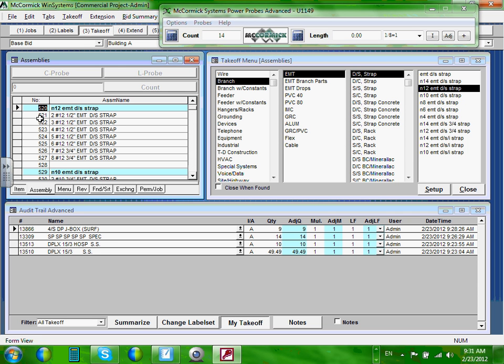Okay, we're going to do that over what I've done. Okay, so I'm going to go branch circuit. I single-handedly, Mr. Curdy, decided to use EMT, which is 99% of what you guys are going to be using. EMT. DS is the strap that comes with it, steel strap. We're going to click the strap, the first one. And here's my option. Number 14 conductors. All the conductors are here, number 14. Don't do that. It's usually number 12. That's your default. Because almost always your branch circuits are number 12. Your branch circuits are always number 12. Cool? All right, so double click on this.